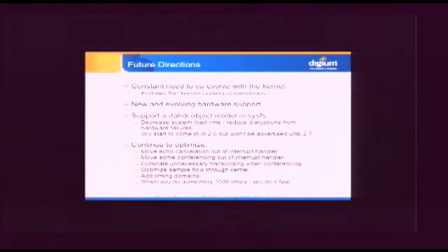Adding timing domains, like I was talking about with the devices, for the domains between the spans. And just, when you're running the interrupt handler 1,000 times a second, microseconds count. You shave a few microseconds off here, you're getting percent of your CPU to do the work that you want to do up in Asterisk, as opposed to just processing the interrupt handler. So that's the rapid-fire DAHDI, but I can go into depth on anything else if anyone's more interested.